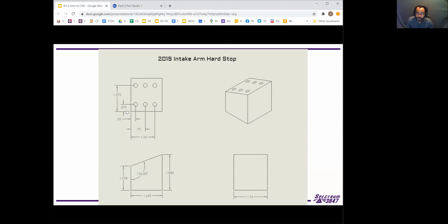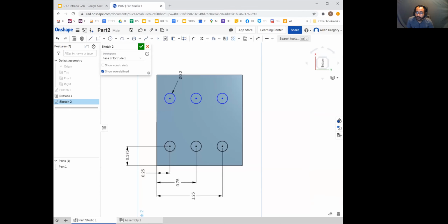And our final dimension here is 1.375 from this far wall. So these are an inch apart. So we're going to do that, and we can do it here. We could put these as an inch apart if we wanted. You could also do the 1.375. It really doesn't matter as long as you get the right dimension. All right, because if I draw a dimension from here to here now, it's still going to show up as being the right dimension. It's going to be grayed out because I've already basically dimensioned it by having these two be added together.